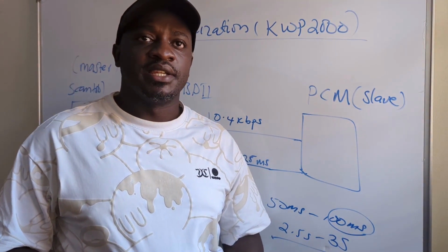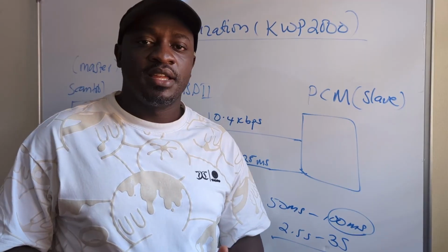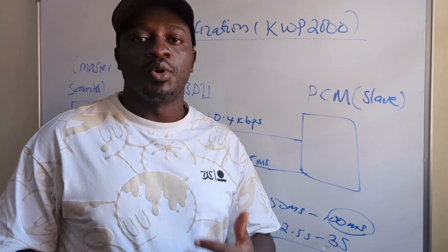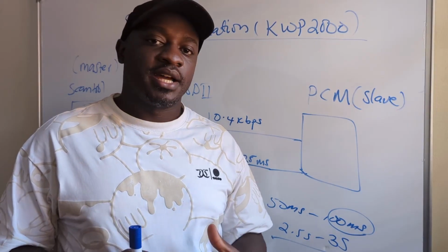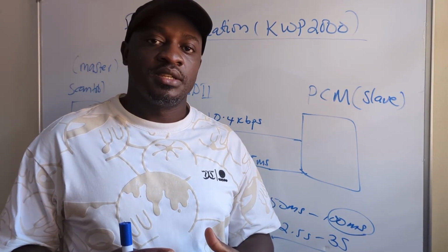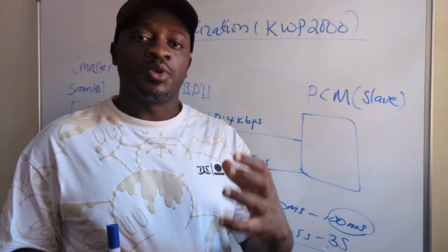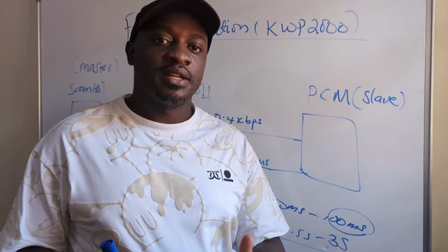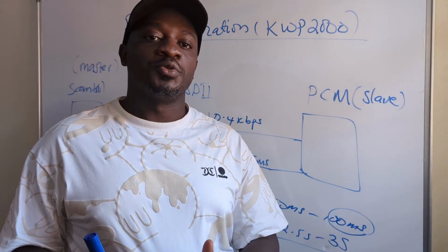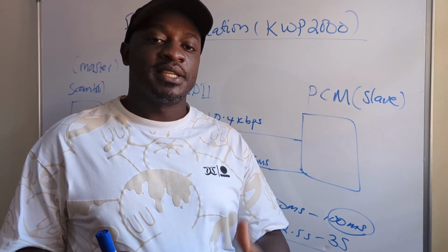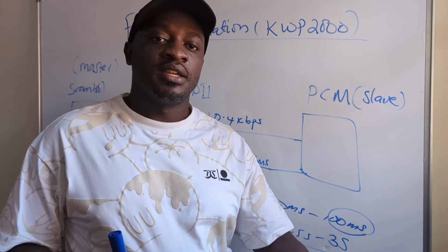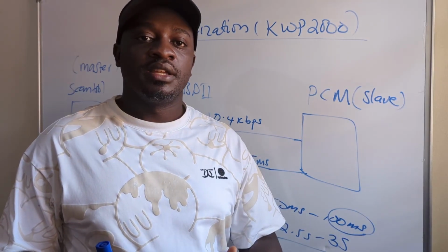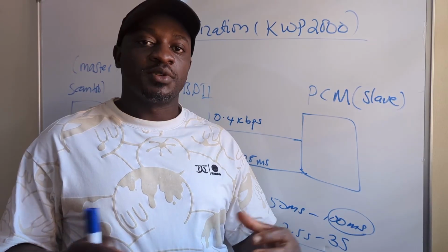Someone out there may be asking, as a technician, do I really need all this? Yes, you do. Because if you don't understand how the system works, or if you don't know what to expect on the waveforms on that network, it will be hard for you to know whether the master is transmitting or whether the slave is responding, and all those components will tie together.